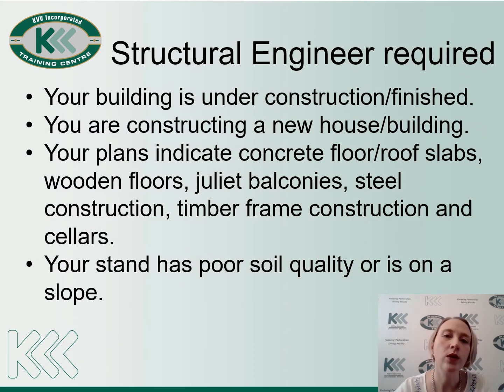The municipality will also require a structural engineer certificate. This is always a requirement when your building is under construction or finished, when you're constructing a new house or building, and when your plans indicate concrete floors, roof slabs, wooden floors, Juliet balconies, steel construction, timber frame construction, and cellars. If your stand has poor soil quality or is on a slope, you will also require an engineer certificate.